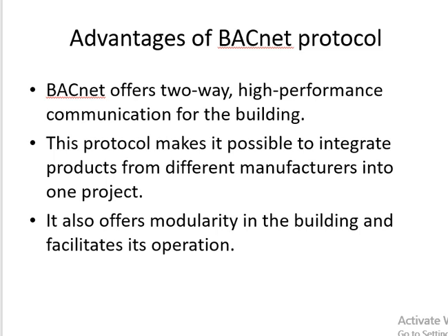And it is a data communication protocol that is used to build an automated control network, known as BACnet or Building Automation Control Network. This data communication protocol is both an ISO and ANSI standard used for interoperability between cooperating building automation devices. BACnet protocol includes a set of rules for governing the data exchange on a computer network that simply covers everything from what type of cable to utilize to how to form a particular command or request in a normal way.